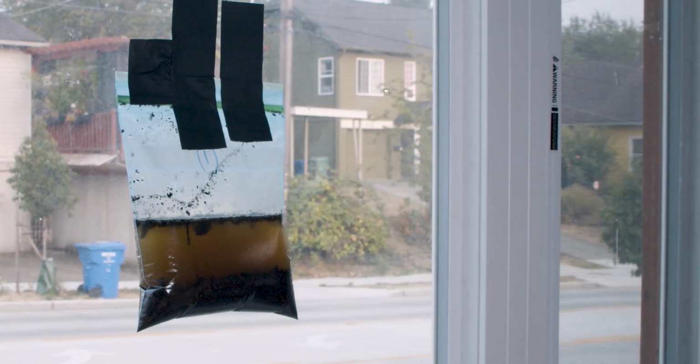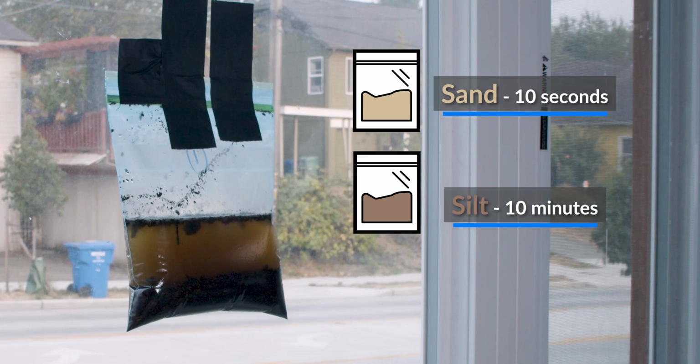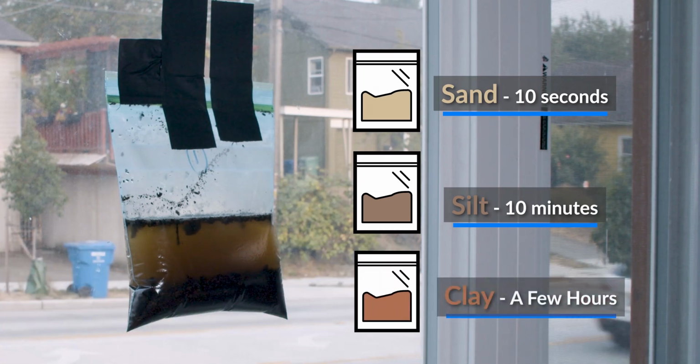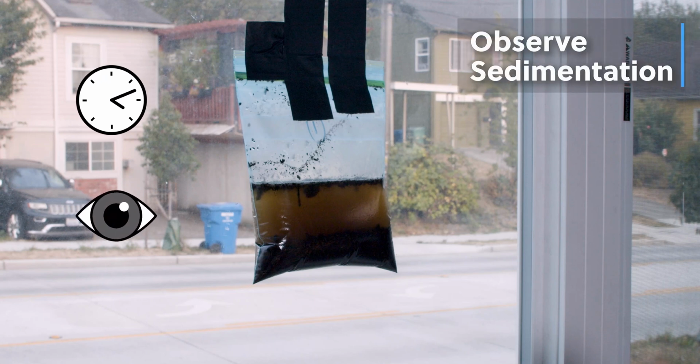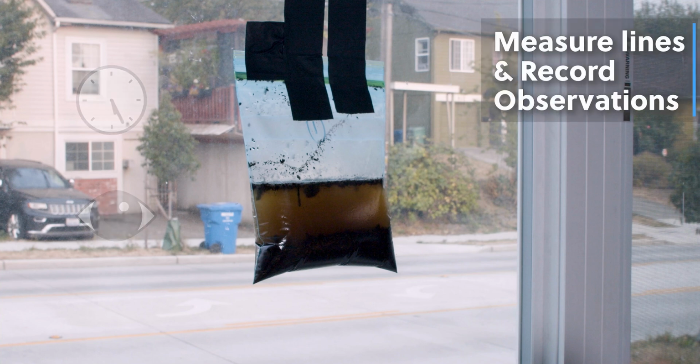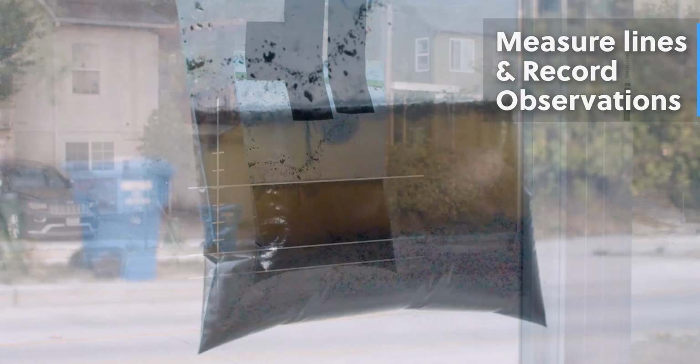Sand particles settle quickly within about 10 seconds, and silt particles settle within about 10 minutes. Clay particles take a few hours to settle, and any organic material will float at the top. After an hour, or the next day, students observe the finished sedimentation. Have students draw lines on their sediment bags to mark the heights of different soil parts, then measure the heights of their lines and record them on their activity sheets.